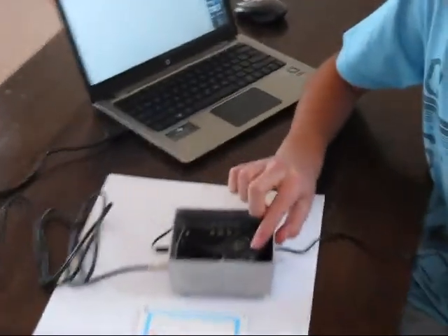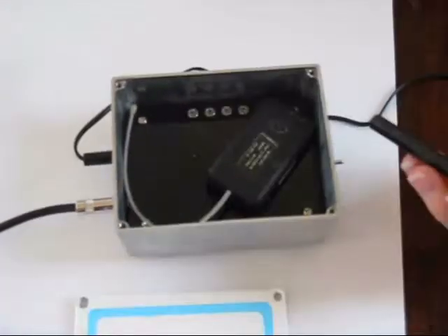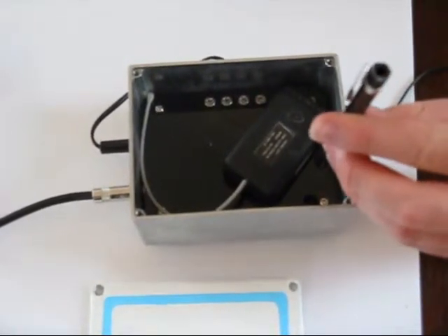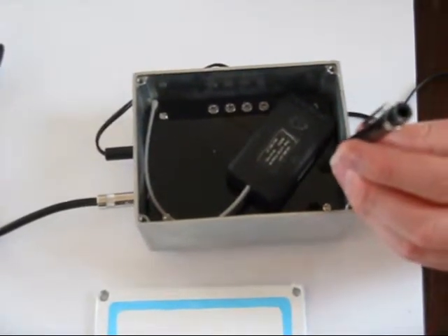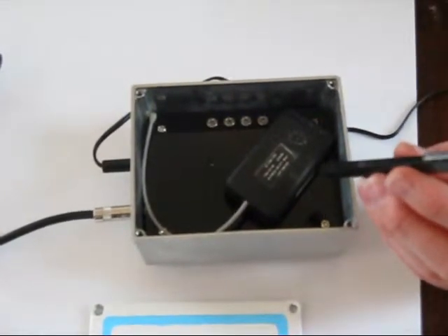To turn the transmitter on, you'll need to take the magnet pen and hold it up to the little dimple in the transmitter's epoxy. Take care not to get confused with the programming port. Hold the magnet pen up to the little dimple in the transmitter's epoxy until the bug finder stops continuously beeping.